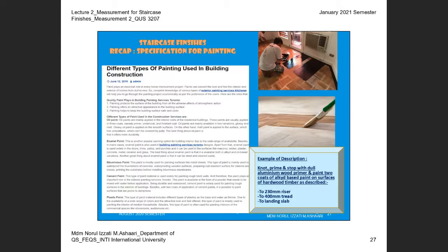And I also highlighted again the example where you have the finishes that are made from timber. For those who cannot remember, you can go through the example and read through all of these, so that you can take note that the timber also requires an actual specification, either varnishing, or oil base, or aluminum base.